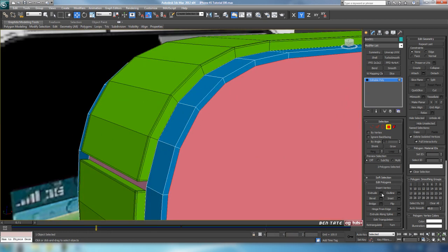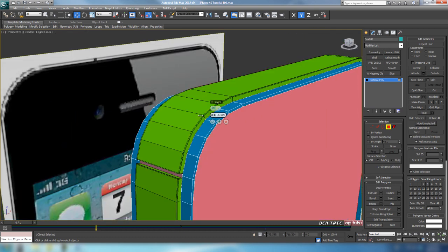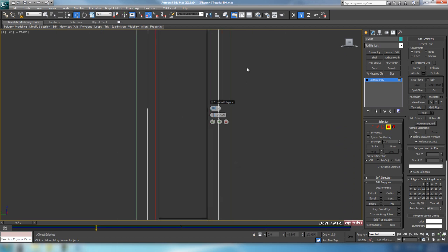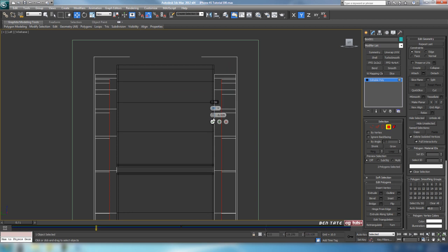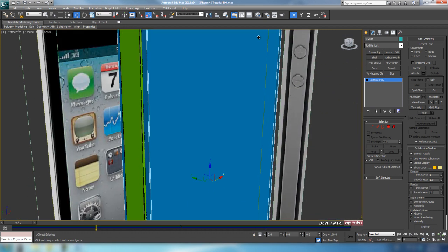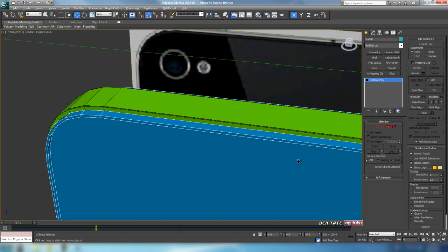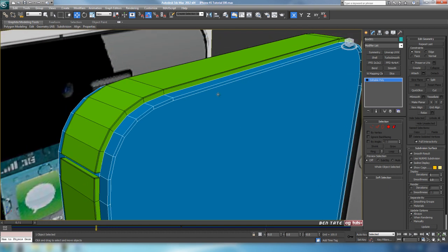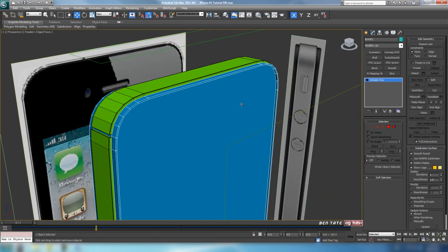And we'll just extrude these polygons in. So open up extrude there, and we'll just take it down to a negative amount. I'm going to push these in a little bit farther than we actually need to, because we are going to have a separate piece of glass that goes on each side. I just want to make sure we have enough room. So we'll push those in maybe like that, around -4, so it should be good, and okay. We'll probably come back to the main piece after we have these buttons and everything else cut into this outside border. So let's hide this one more time.